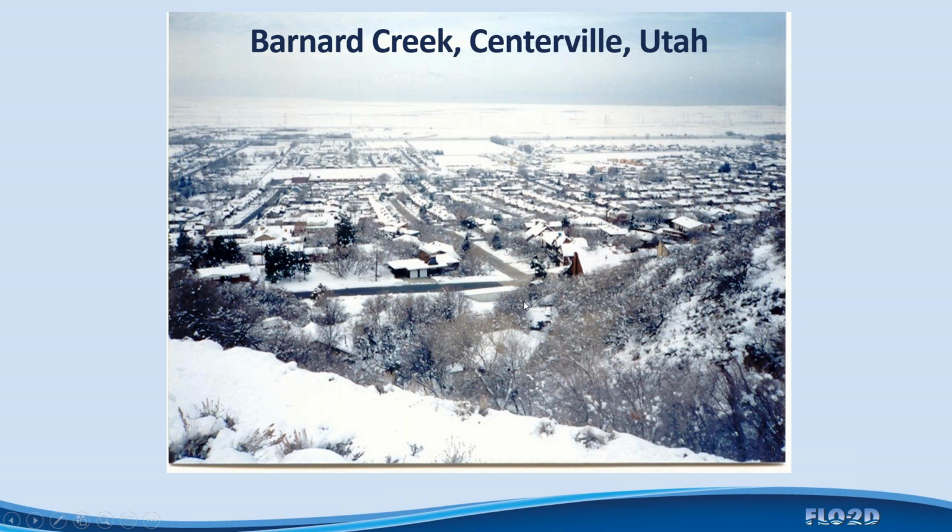And in this case, this alluvial fan was subjected to historic mud flow events. And they built a little debris basin here, probably just off the cuff back in the 80s, 90s. And they didn't have any practical means of estimating this, because the mud flow event for the 50-year event is like 6 orders of magnitude of what could be stored in this little basin. So anyway, there's a little bit of deposit in this basin, and it overtops and goes right down this very steep average 10% slope down the street through these houses and stuff, and then flows directly into the school.